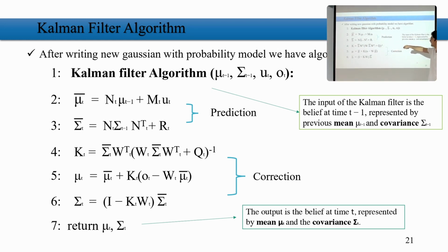But what was the benefit? The benefit is that you don't need to do anything. You don't need to say, okay, my robot is... You can of course put some weights over here, but the Kalman gain already calculates it automatically for you based on the amount of error of the control command and the amount of error of the observation model that you have.